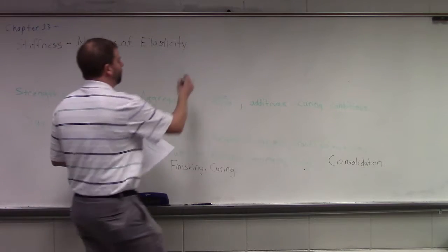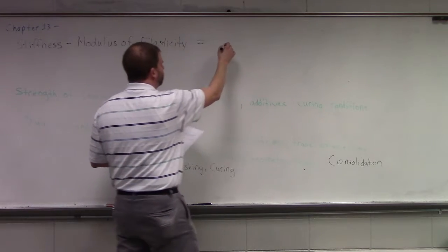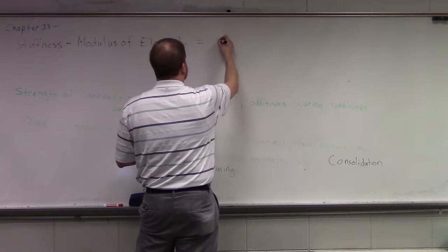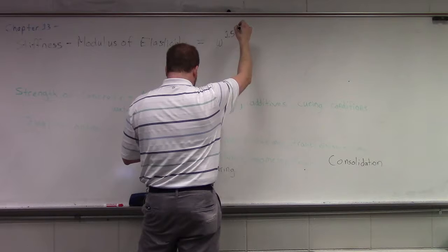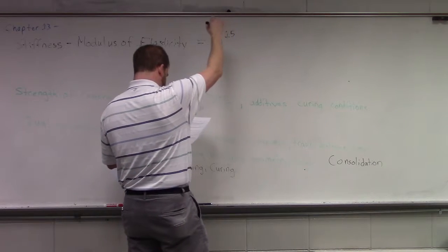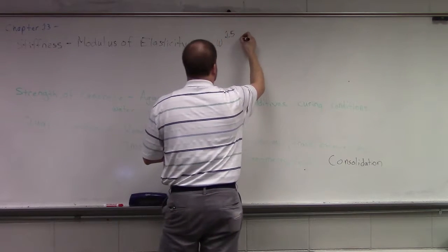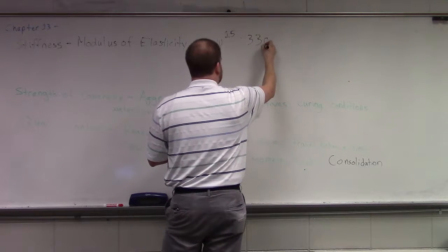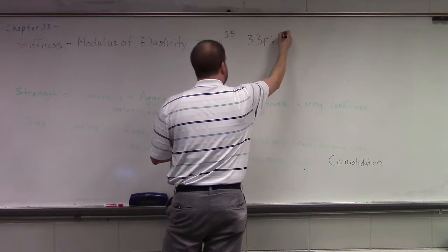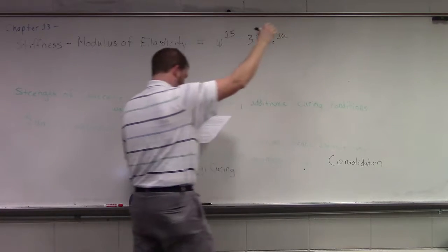Typically speaking, from a design standpoint, they start out by saying the modulus of elasticity equals W raised to 1.5 times 33 times f'c to the 1/2.